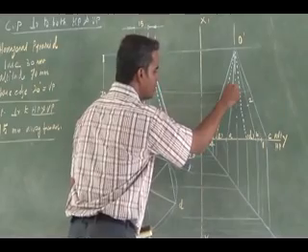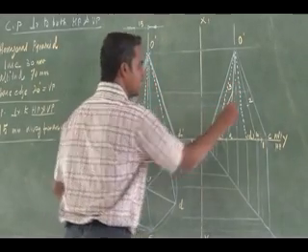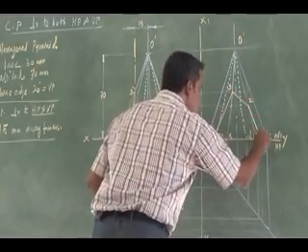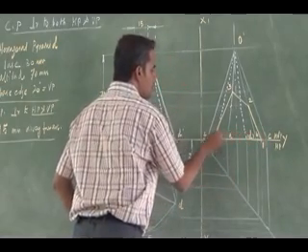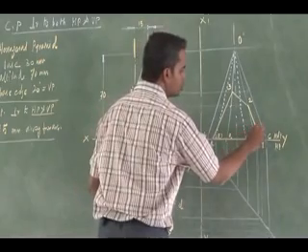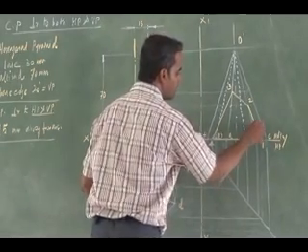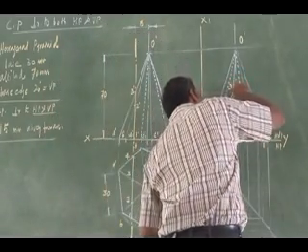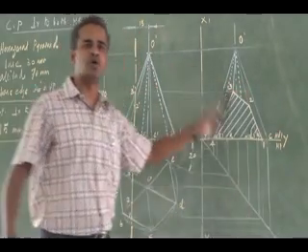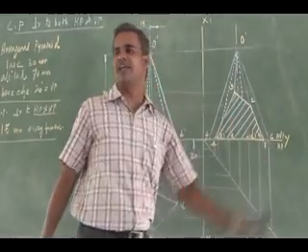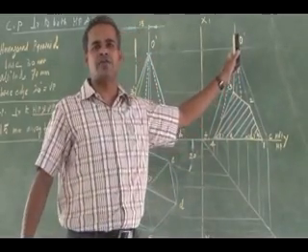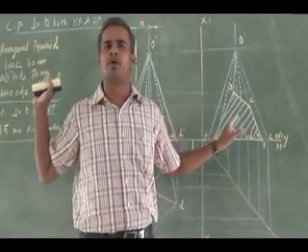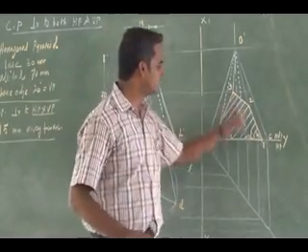Right. So 1 and 4 connected like this, 2 and 3, then 1 and 2. So this is going to be my true shape, right? This true shape, you can hatch it. This is my true shape of section, which forms in the sectional side view itself. There is no apparent section; both the apparent and true shape fall on the side view itself. If the problem is given, just draw the true shape of the section in this problem, which is enough for me. Just the section alone is enough.